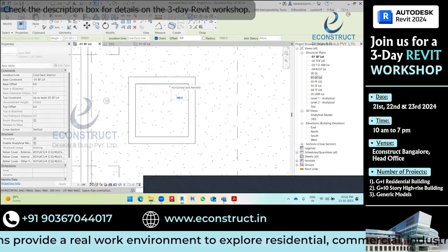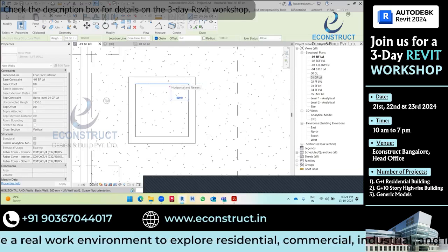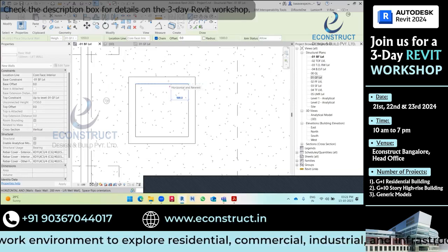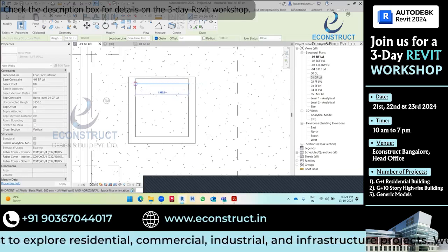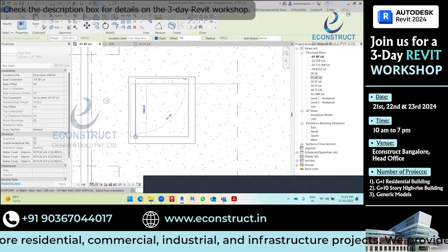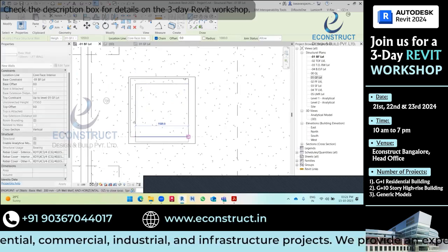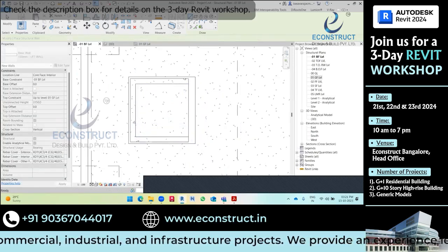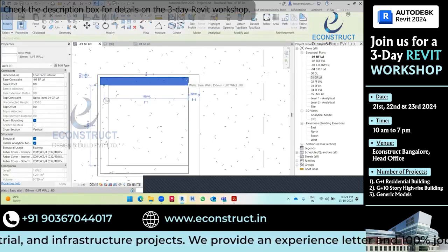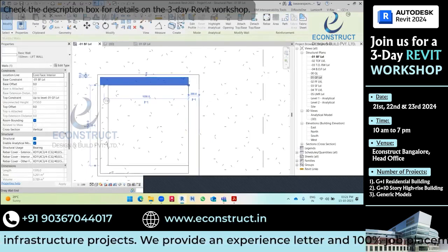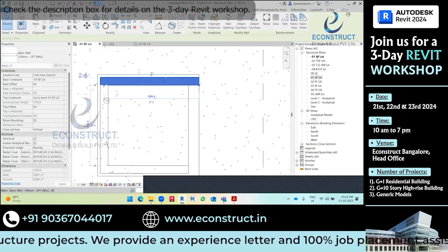See, now it is coming inside that location line, right? So just click the space bar and it will flip. Like this, and like this. Now you just extend this wall 6 inch, or else 8 inch. You extend this wall.